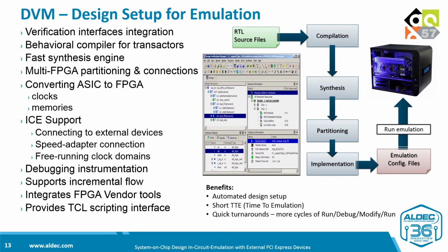DVM, Design Verification Manager software, is a tool for design setup automation. It will guide you starting at RTL sources compilation through synthesis, partitioning, and FPGA bit file implementation. DVM provides two distinctive design flows, one for emulation and the other for prototyping. In emulation mode, that also includes simulation acceleration, DVM integrates verification interface with your design and provides behavioral compiler to convert transactors, monitors, and similar test bench components to FPGA.